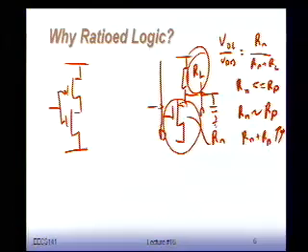If I make them very large, I will have less leakage current. But that might impact your performance. So there's a bunch of trade-offs that you have to play here. Do you care about static power dissipation? Do you care about noise margin? Do you care about performance? And that's the optimization game we're going to play here.